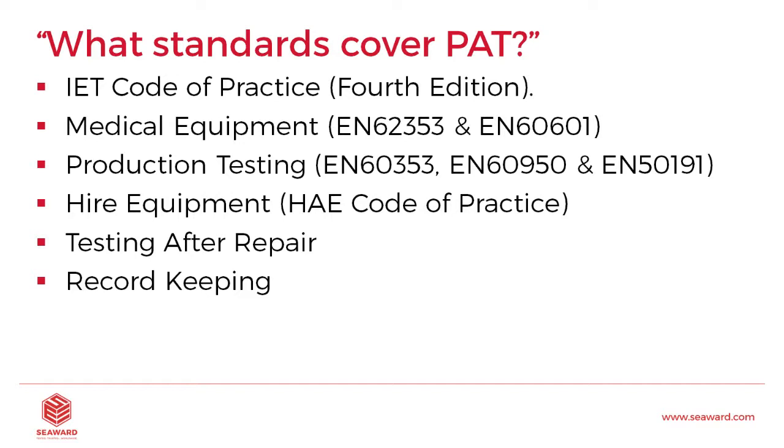One other question that comes up quite a lot is obviously testing medical equipment where you have patient applied parts. Some deem this to be under PAT testing, but it actually has a standard or two covering it in itself. So medical equipment, you have the EN 62353 and the EN 60601. We do have a guide to testing medical equipment through our brand of Rigel. So if you are testing medical equipment, definitely worth a look there.